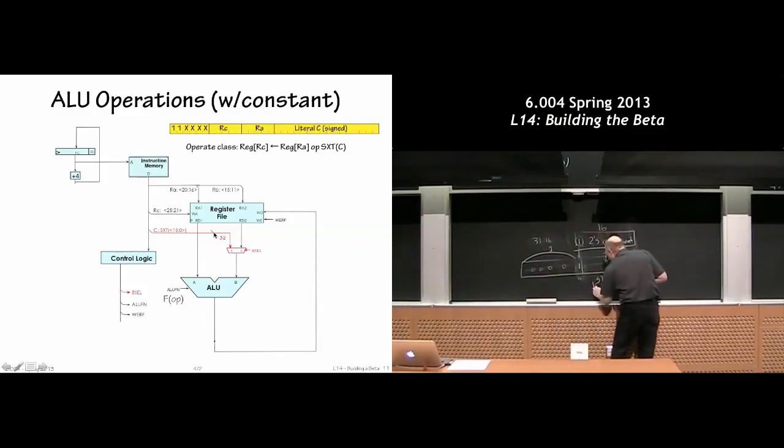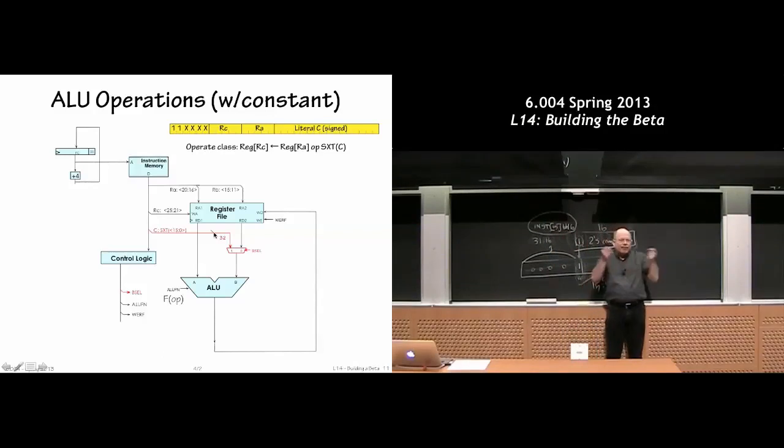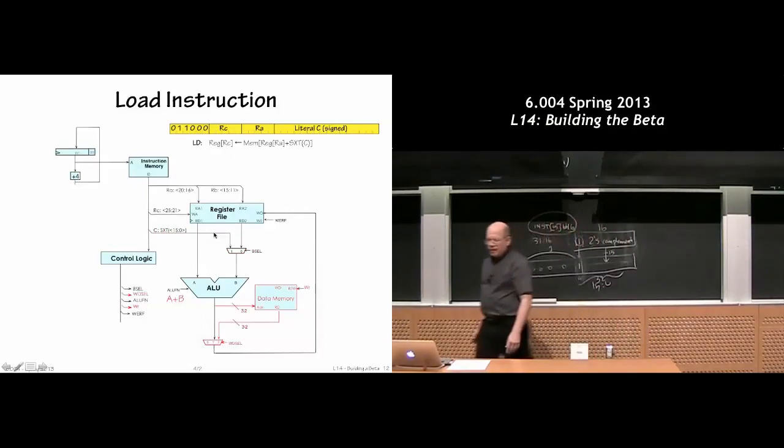So this is bits 15 down to 0, the bottom 16 bits. And so the high order 16 bits are basically the instruction field, number 15, replicated 16 times. That's the JSIM way of producing 16 copies of a particular signal. So that's what sign extension means.